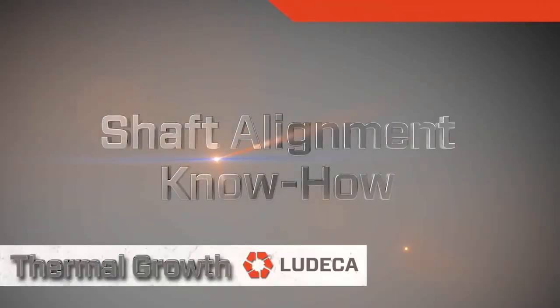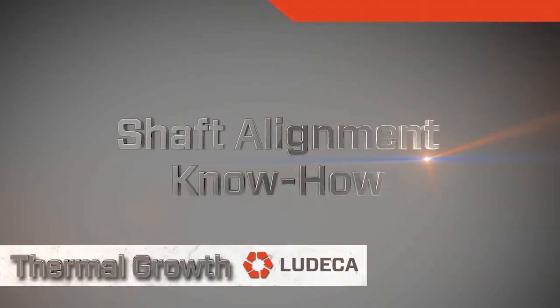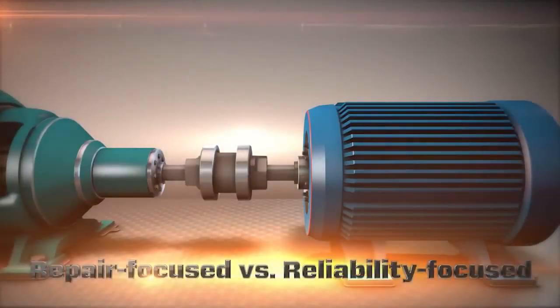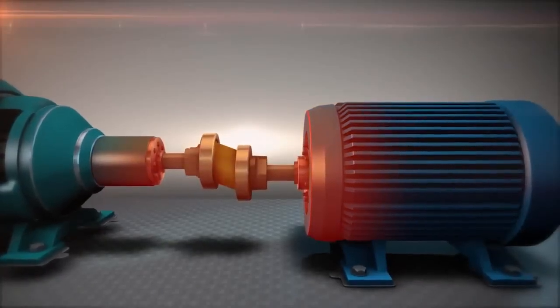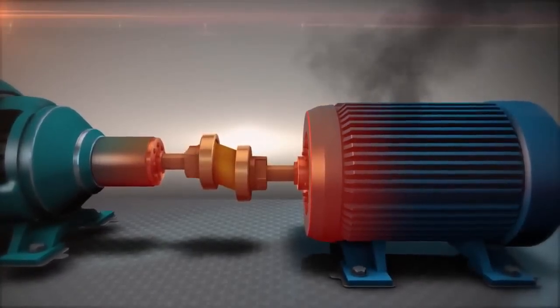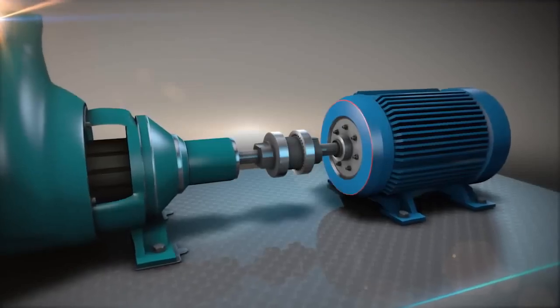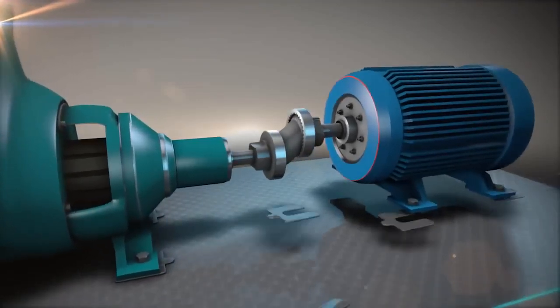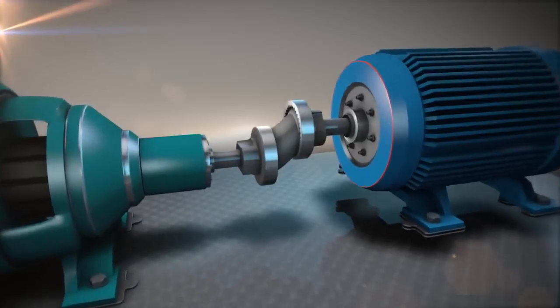Shaft alignment know-how. Thermal growth, positional change. Not accounting for positional change in rotating machinery is a big reason why maintenance departments stay reactive instead of proactive. When rotating equipment runs, it heats up and undergoes positional changes. This can occur due to thermal growth, dynamic load shifts, pipe stress, and other factors. Therefore, it may be desirable to deliberately misalign the two shaft center lines when cold and stopped by the correct amount to compensate for these anticipated changes.